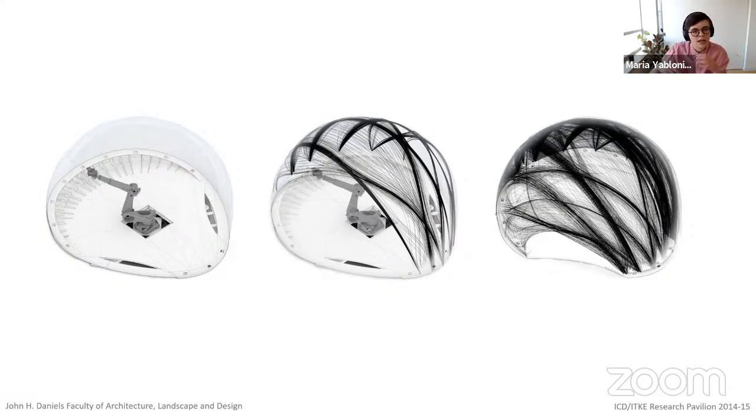And throughout that process, as the pre-impregnated carbon cures, you eventually get a pretty solid, stiff shell. So once the shell is thick enough and stiff enough, you can actually remove the air pressure.